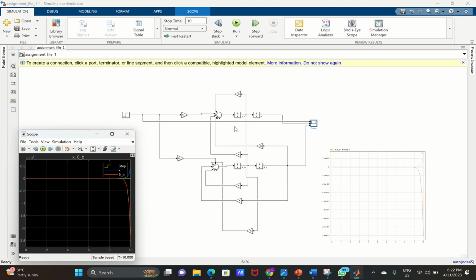In conclusion, there are a few controllers that we've been able to look at that could help out to stabilize the system, hence have the robot balance. The first one is the state feedback controller, and the second one is the PID controller. Manipulating the different values and variables in those two controllers, we could be able to have our robot balance and attain stability.